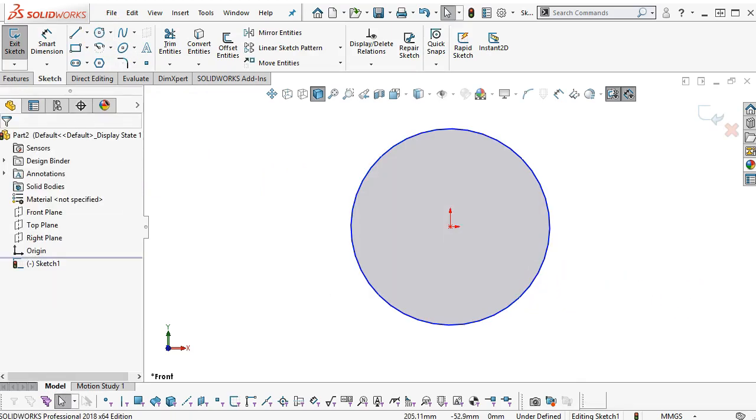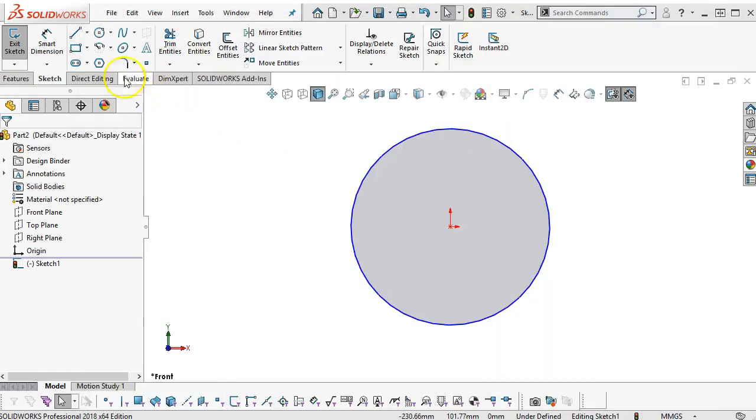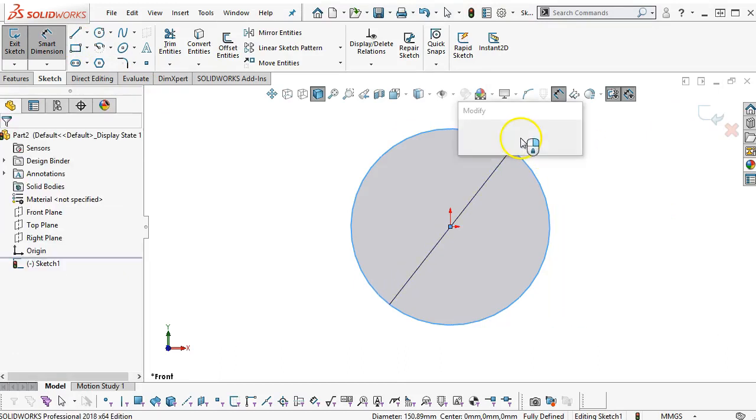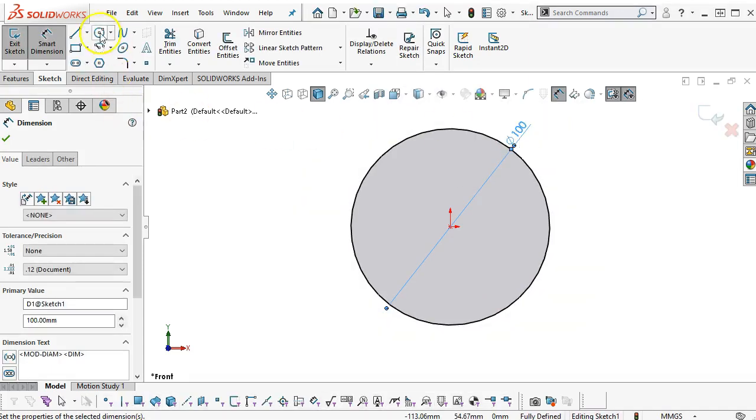So let's fly that drawing back in. Alright, so if this is half of a part or a clamshell, then we may end up creating both pieces as bodies. If not, it'll be simpler to create the circle, create the polygon, split it, and select the region. So the dimension here was 100 across the diameter, so we'll stay with the 100.